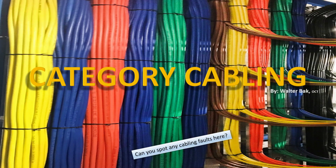Other people put in about the same amount of time. And one person said that once, within the 30 years of their working, there was a situation where crosstalk happened because two data cables were straight beside each other. Now, crosstalk can happen, but also when you make a mess out of cables, just randomly arranged, you could probably create more damage by doing micro bends in the cables.